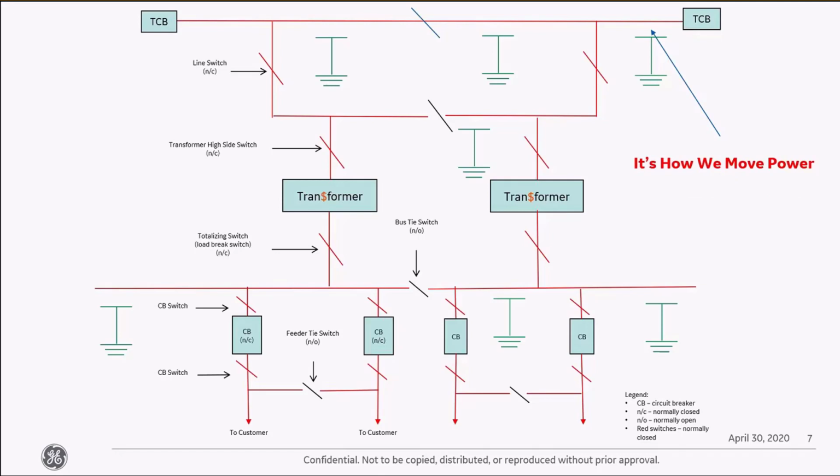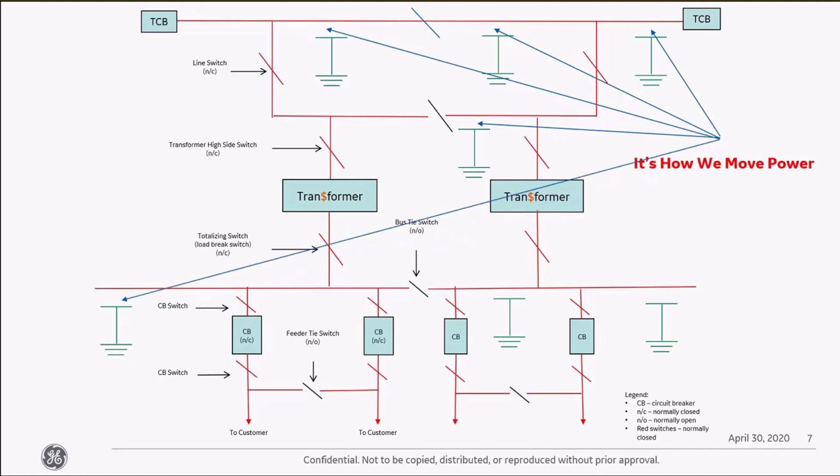So if you think about it, if you've ever seen bus work coming out, what's it got on it? It's got insulators. And what are the insulators tied to? Earth. What is that? It's a conductor, an insulator, and a conductor. Isn't that a capacitor? I just put some examples in here of the fact that bus work is supported by insulators, which are tied to earth, which make them capacitors. Typically not in the same function that we think of capacitors, but bottom line, that's what it is. That's how you get power out. If you did not have that separation, you wouldn't be able to move power.